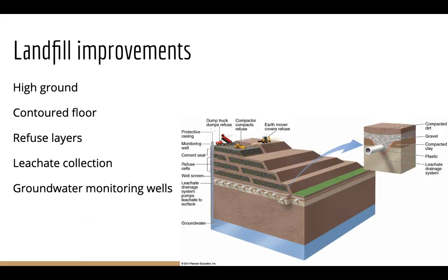Right. So some ways that you can improve a landfill or have a better, more sanitary landfill: it should be on high ground. So this makes it above the water table. That way if you get flooding, you're not going to get water seeping into your landfill. You should have a contoured floor. Right? So a contoured floor, like a sloped floor,